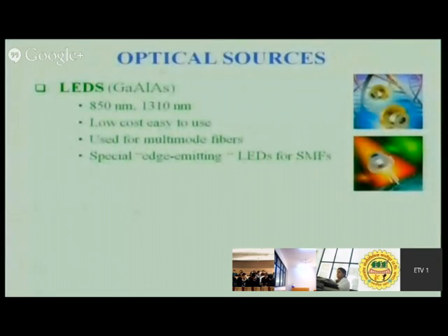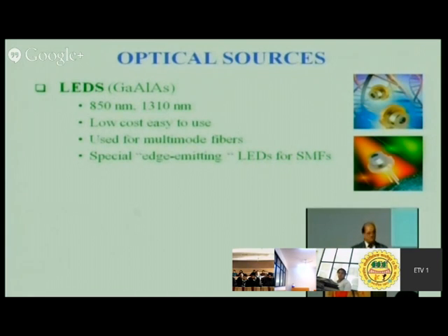Then we have optical sources. I mentioned we can have the LEDs. A lot of effort is also required; we need parallel development in optical sources. These are mostly made from alloy semiconductors, maybe gallium, aluminium, arsenic. The first device is made from gallium arsenide, which works at 850 nanometer. There can be binary alloys, ternary alloys, quaternary alloys. Accordingly, we need them for 850, for 1310, or for 1550. We have to see how we can use different alloys for better and better properties of an optical source.